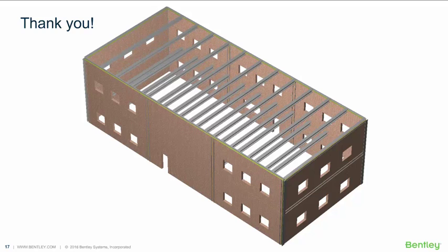There was another question about, I believe, when you do that, is the entire height of the wall going to be lumped to the roof level? And the answer there is no. RAM Frame does that partitioning for you. We can double check on that, but you should see that it is in fact excluding the lower extents of this wall mass.